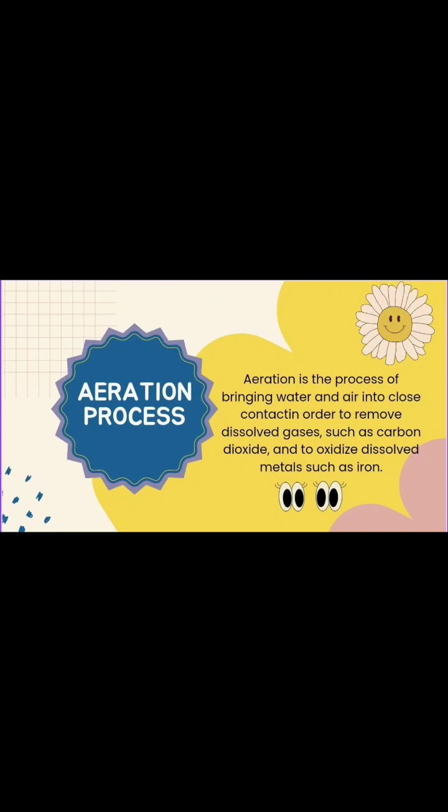First process is the aeration process. Aeration is used to eliminate unneeded dissolved gas in Sungai Langat such as radon and carbon dioxide. Unpleasant taste and odor causing substances from raw water such as methane, hydrogen sulfide, and volatile organic compounds. It is also an effective method to raise the pH of water to facilitate the coagulation process. This method can also precipitate the dissolved iron and manganese from the incoming water. However, aeration is not effective to remove heavy metals and pathogens such as bacteria and viruses.